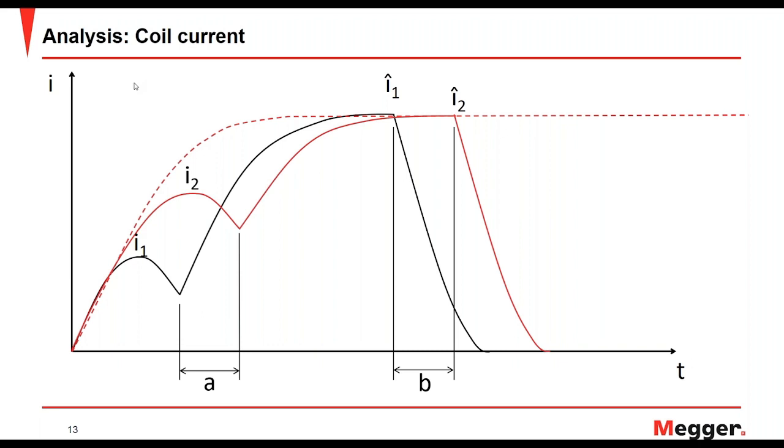This usually happens in first trip tests. When you do this, you find these singular differences in the test. But once the breaker is operated once, and then twice, three times or four times during the conventional timing, this condition will just clear away, because during operation the breaker gets lubricated and removes any rust or dust inside these mechanical parts.